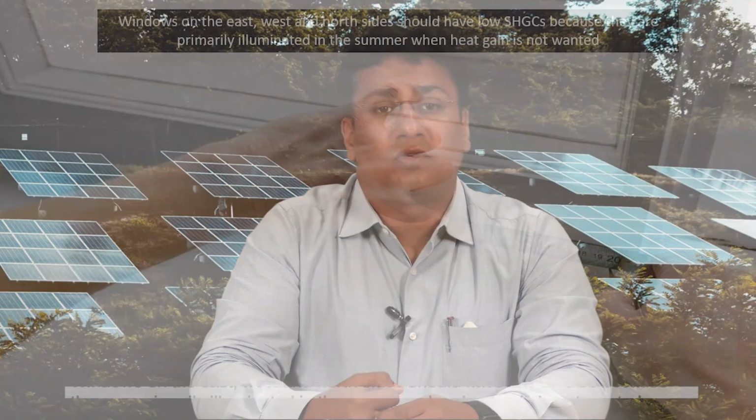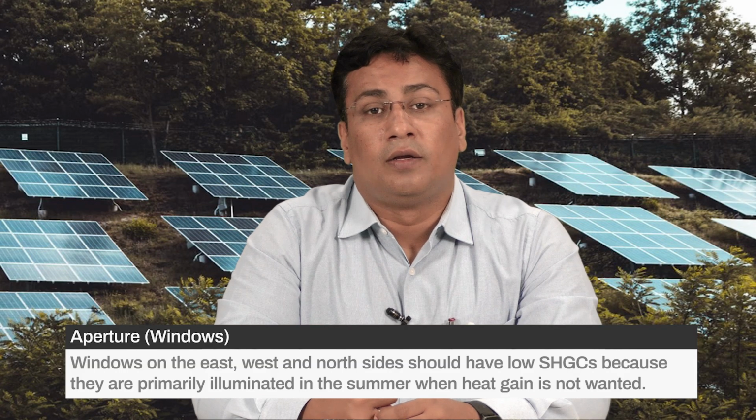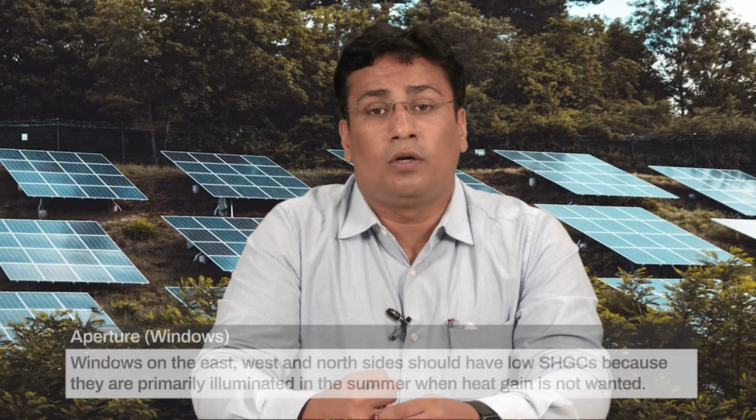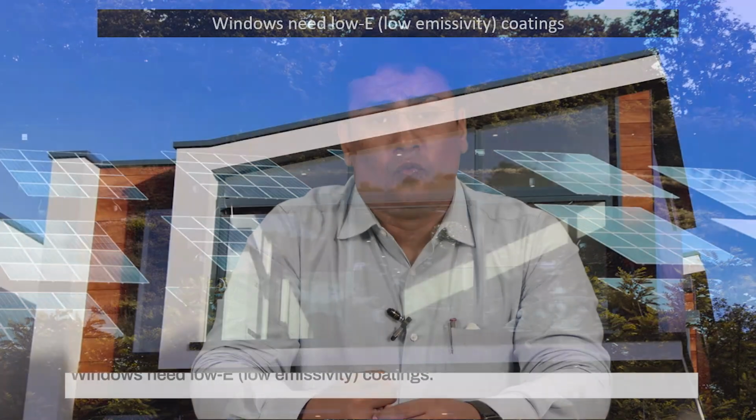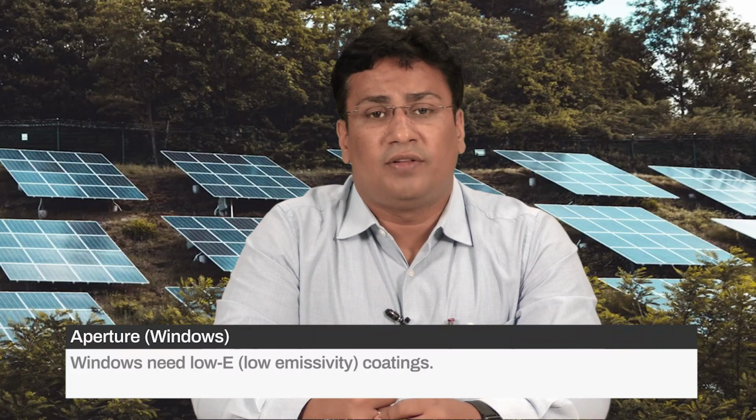Next, windows on the east, west and north side should have low SHGCs because they are primarily illuminated in the summer when heat gain is not required or wanted. Next is that windows need a low emissivity coating. What is the low emissivity coating? Low E windows limit the passage of heat by radiation, blocking interior heat from leaking out in the cold and blocking exterior heat from entering cool interiors.